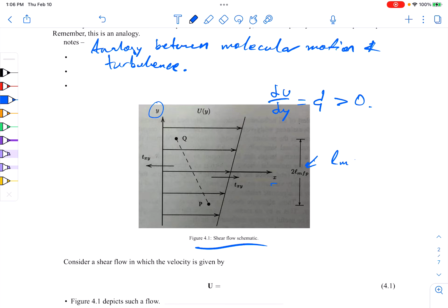L, mean free path. So people like Boussinesq and Prandtl were actually looking at the turbulence problem, not like we think of it today as a continuum problem, but more like these clumps of little molecules flying along. And if they travel in the x direction by, say, a unit 1, they would also travel and expand as a clump and maybe diffuse in a direction y. And so that mixing length originally was thought of as L, the mean free path. That'd be like the mean free path that these molecules expand as you go downstream in the shear layer.